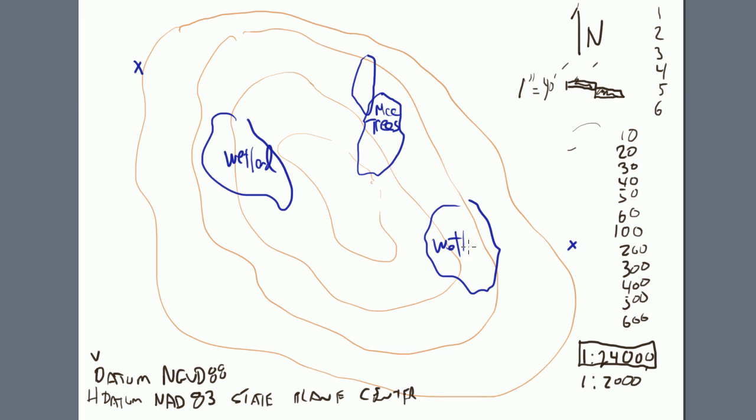A wetland. So in an alignment design, you have to pick what you're going to avoid as much as what you're going to hit. And you generally have a goal to go from one place to the other. Your next step, typically, I will say in Civil 3D or anything else, is to draw straight alignments through. Not straight from here to here, but you're going to be drawing your plan in tangents and ignoring the curves, doing the curves next. See if I can put this in black, which I can't. So I'm going to see if I can then put this in purple. How's that? Figure out these colors later.